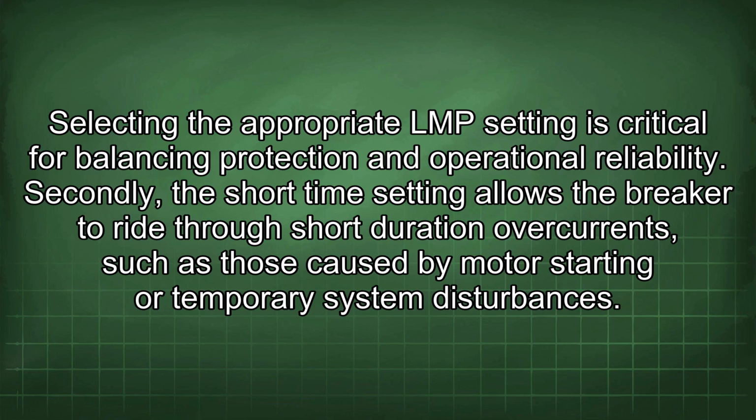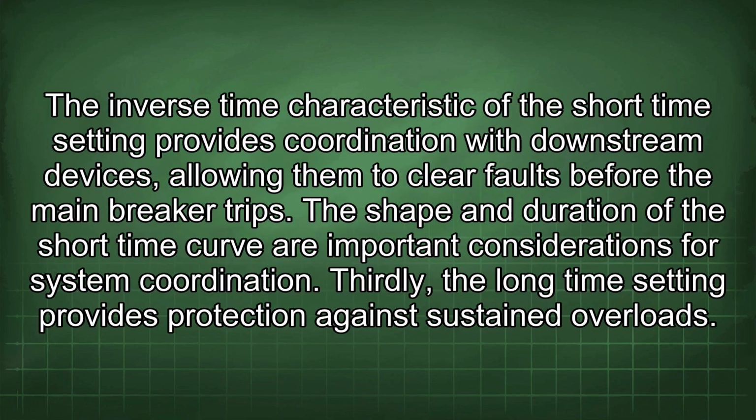Secondly, the short time setting allows the breaker to ride through short duration overcurrents, such as those caused by motor starting or temporary system disturbances. The inverse time characteristic of the short time setting provides coordination with downstream devices, allowing them to clear faults before the main breaker trips. The shape and duration of the short time curve are important considerations for system coordination.